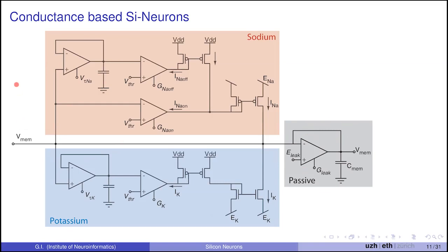So what we do is we inject constant current into this node, which is the membrane capacitance node. In fact, it's connected to the membrane capacitance. If we inject constant current, this capacitor will charge up. And then if this follower integrator is working in subthreshold, it will actually approximate first order differential equations. So this is just going to charge up Vmem exponentially like an RC circuit.